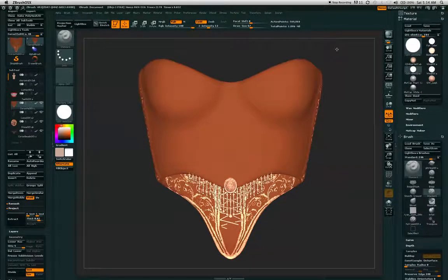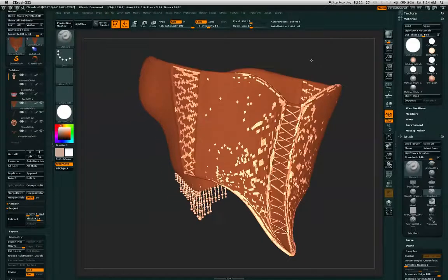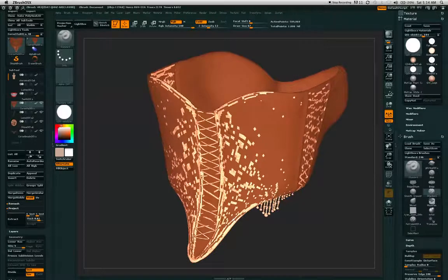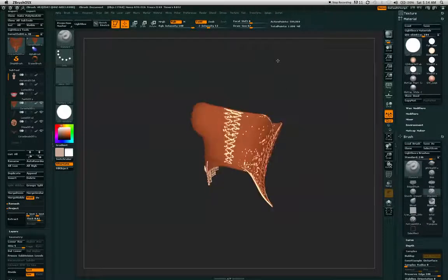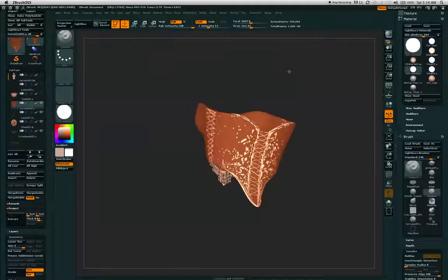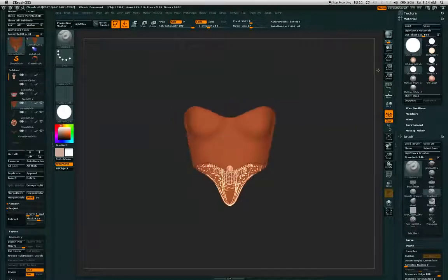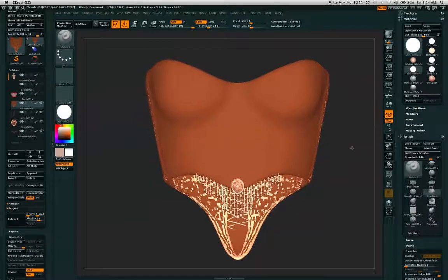Although it's not good to render while in actual mode, because it will make your textures and details a bit bitmap. You want to be on AA half if you're rendering out your model. Actual works really well for small detailing on your 3D object.